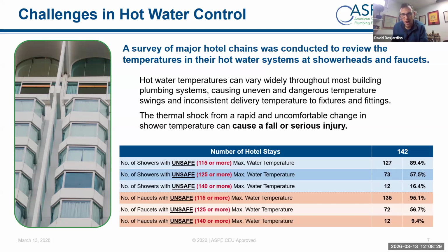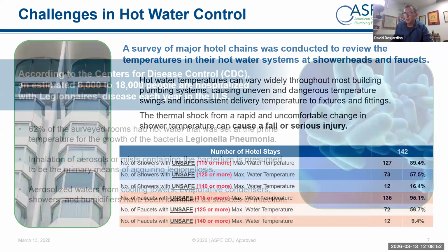So that's quite hot. Separate from this, recently, probably 2 weeks ago, I was at a facility with a mechanical mixing valve in place, and some people were fooling around with the valve. He showed me that there were temperatures leaving the shower at 190 degrees. So you can see, yeah, I know. I'm like, whoa. So anyways, a good candidate for some mixing valves, yes.